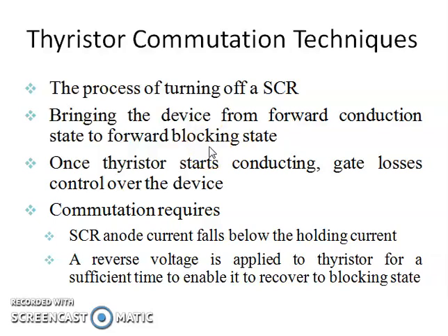For the purpose of power control or power conditioning, a conducting thyristor must be turned off as desired. Once the thyristor starts conduction, the gate loses control over the device. Therefore, external means may have to be adopted to commutate the thyristor. Several commutation techniques have been developed to reduce the turn-off time of the SCR.